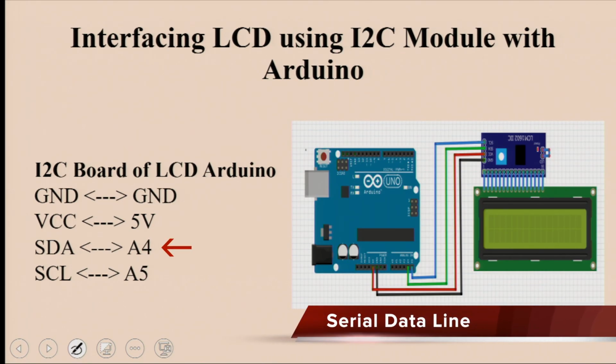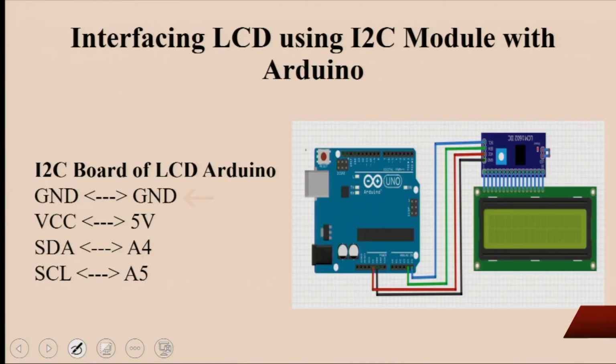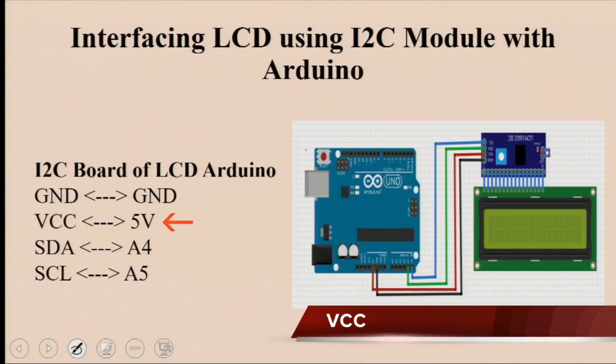Along with this, we have 2 more pins, that is ground and VCC. So, now you are left with only 4 connections. This is a very easy interface for you to connect any LCD board. This same chip you can utilize even for connecting a 20x2 LCD or 20x4 LCD as well.